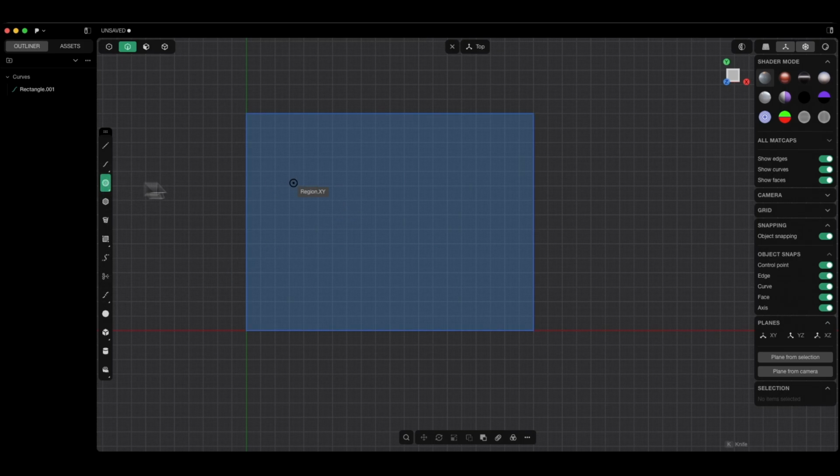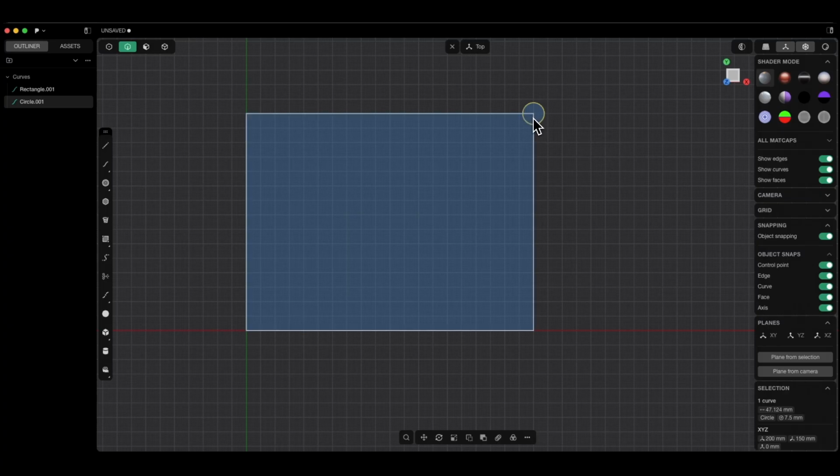One of them I already showed in the previous example. Simply create the geometry at some specific point. For example, I'll create a circle with a 15 mm diameter at this rectangle's corner. I set the circle's center at the corner, press Tab to define its diameter, type 15 and press Enter to confirm. And now I want to move this circle so it is offset by 15 mm in the negative X direction and 15 mm in the negative Y direction.